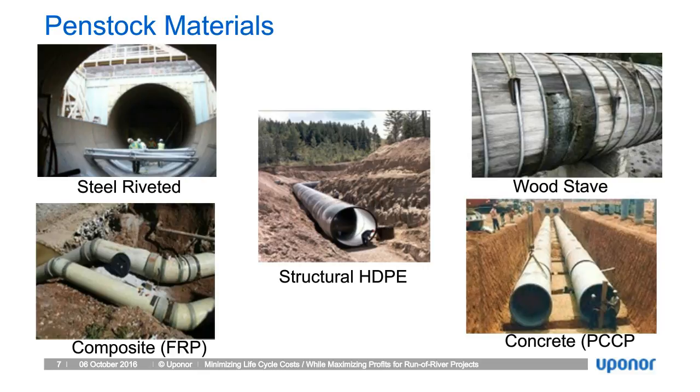It offers a good material for high pressures and comes in varying dimensions. Can be buried or above ground. Wood staves, an awful lot of run-of-river projects, which we'll be talking about today, with wood stave penstock applications. The reason for this is that a lot of the materials were local. They could, from nearby forests, get their resources there, mill up the wood, and then locally install this.